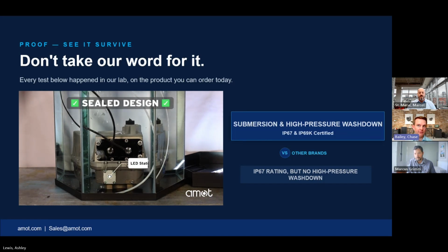So we looked at vibration first. Second, how can we protect this thing from the other elements within the field? A standard actuator is an IP67 rating, pretty standard across all electronic components. But we knew that wasn't cutting it, because there were plenty of actuators with that rating failing out in the field. So we looked at the IP69K rating. This is protection against water ingress, dust ingress, as well as a high pressure washdown situation.